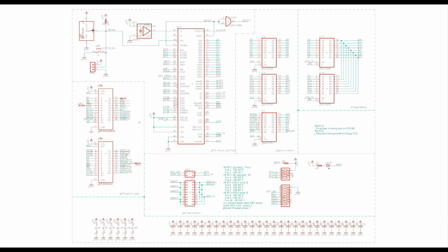The reset is handled by an MCP130, which will automatically reset based on the voltage. Now the address and data bus are multiplexed together, so AD0 through AD15 are both the address and the data bus. So what we will have is a couple of latches here, and when this ALE signal is present, that's address load enable, we will latch the shared bits here, and that will give us the first 16 bits of our address. We'll also at the same time latch the upper 4 bits. That gets us to a 20-bit address, as well as the state bits S0 through S2 and BHE.